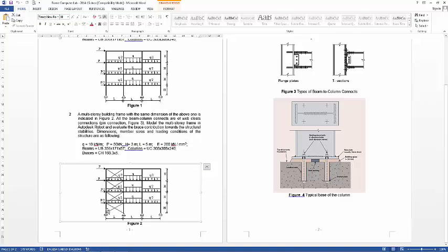So after you set this up, you will get another type of structure, in which the beam and column here are the vertical system, which will take all the vertical loading and transfer it down to the ground. And then the diagonals and the frame here will form a tower. This rigid tower is going to take the lateral loading, so this system is called the lateral system.